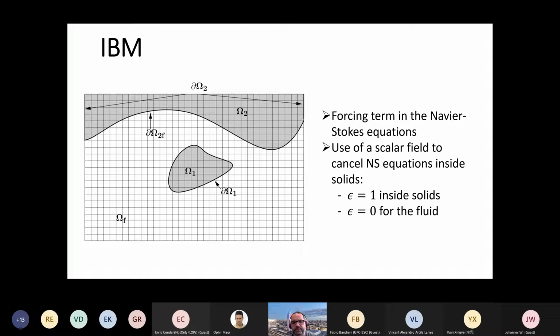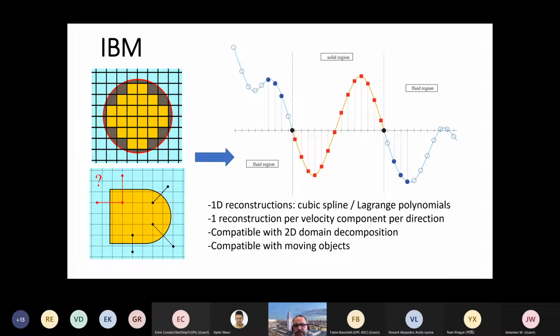The one thing I wanted to touch on is to explain how, when you have a Cartesian mesh like this and the governing equations are dealing with fluid, you add some solid geometry. We do this with an extra term in our equation, and basically we are trying to freeze the velocity inside any solid geometry. So we scan the computational domain, and when we are in the solid, we freeze the velocity to 0. That's the rough idea. I'm not going to spend too much time on this.